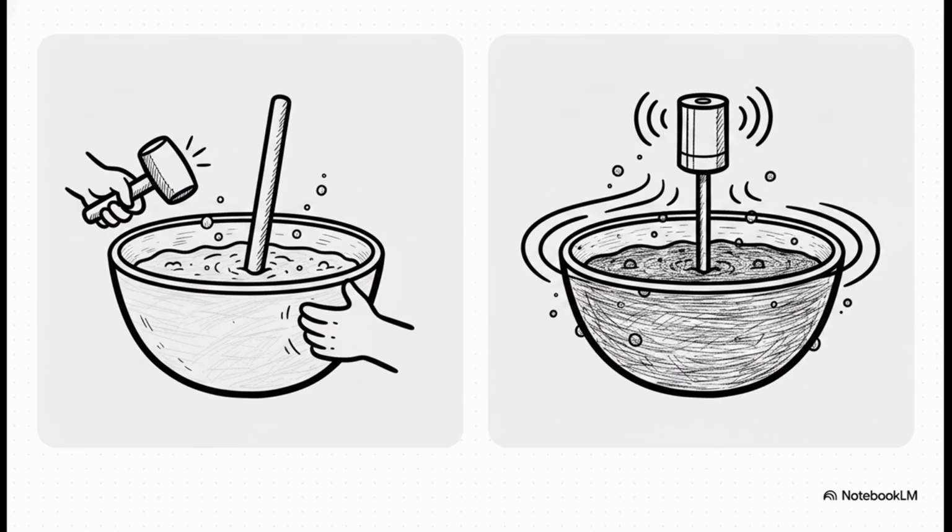If the slump is greater than 40 millimeters, you use the rodding method. You fill the bowl in 3 equal layers, driving the tamping rod in 25 to 50 times per layer, and tapping the sides 10 or more times with that highly specific rubber mallet to close up the voids. But if the concrete is stiffer, with a slump of 40 millimeters or less, you vibrate it in just 2 layers, inserting the vibrator 3 times per layer. The physical labor here is intense but highly controlled, because as the standard explicitly warns, over-vibrating can actually cause you to lose the intentionally entrained air.